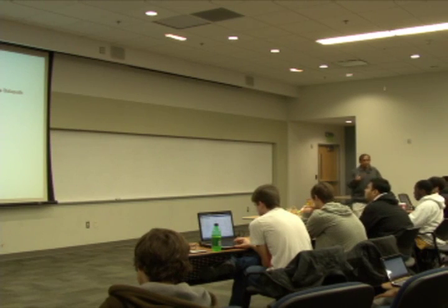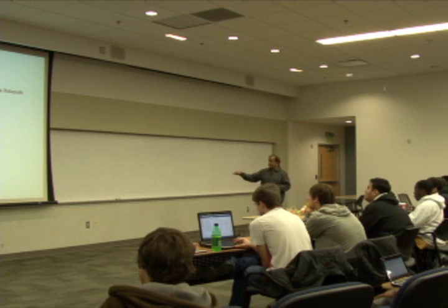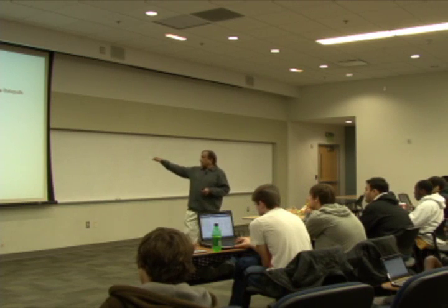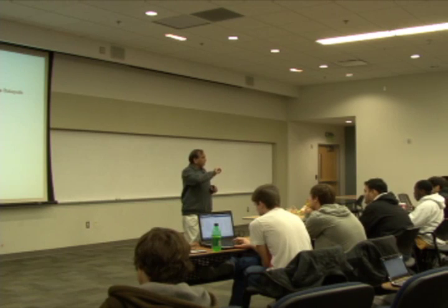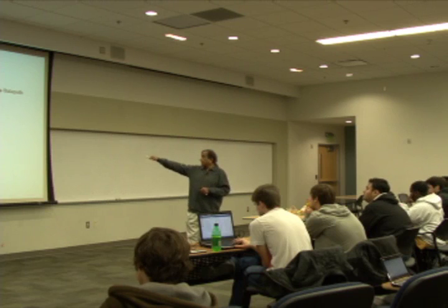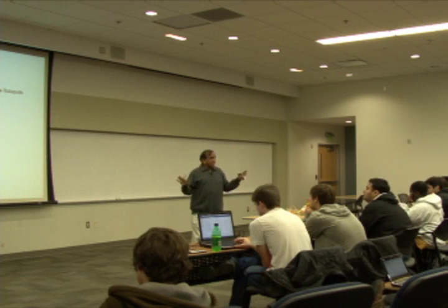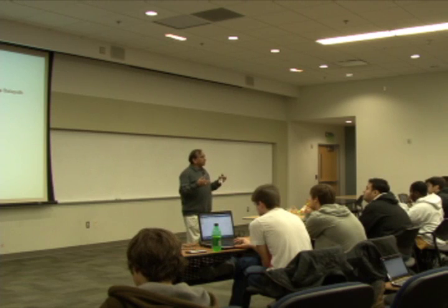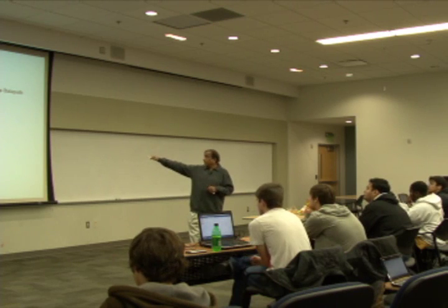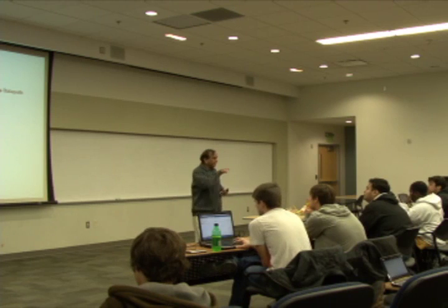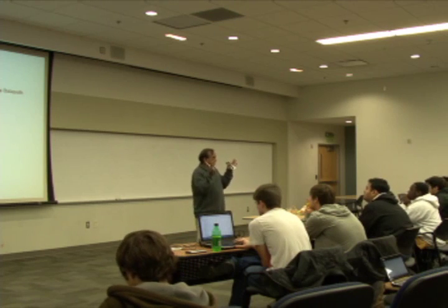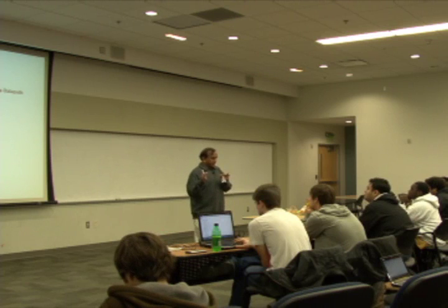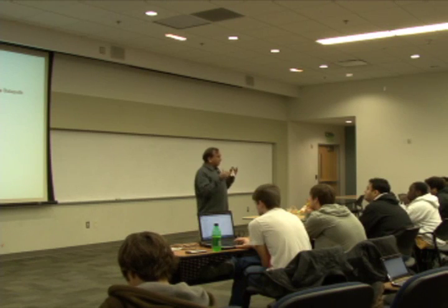and that is what is called a microprogram. Okay? And one nice property of the microprogram control is that all of the control is residing inside this ROM, right? So all the sequences, you basically boiled it down to ones and zeros, and you have stuffed it into this ROM, and that is how you're controlling the entire data path. So if something goes wrong, if you have to debug it, what you have to do is see what signals are being generated in one particular microinstruction and see if that is exactly the signals you want, right? So in terms of maintaining such a design, it's much easier because it is all contained in this ROM, and you program that ROM.